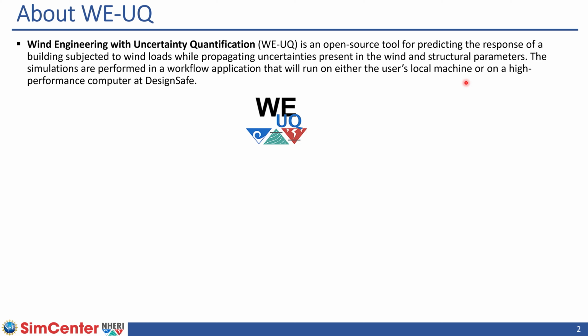Just to give some background about the tool, the term WeUQ is an acronym that stands for Wind Engineering with Uncertainty Quantification, and it is one of the open source tools developed by the NHERI SimCenter for predicting the response of a structure subjected to wind loading. The workflows implemented in WeUQ have special capabilities for modeling and propagating uncertainties present both in wind and structural parameters. You can run these workflows right on your local machine as well as on high-performance computing platforms provided by DesignSafe.